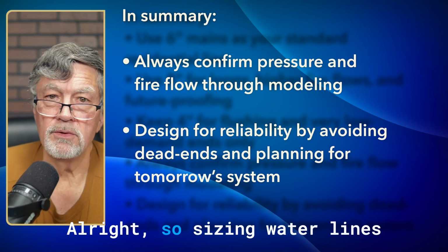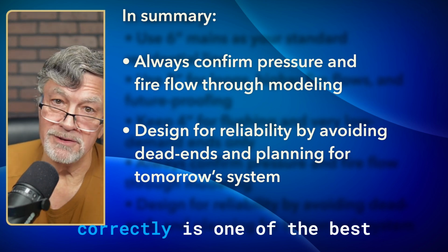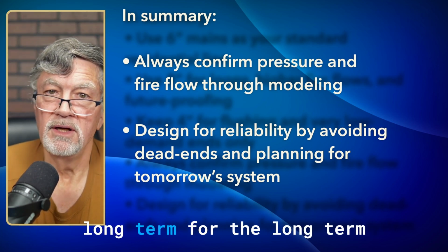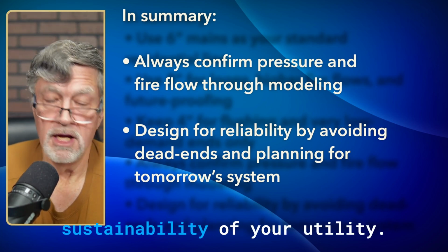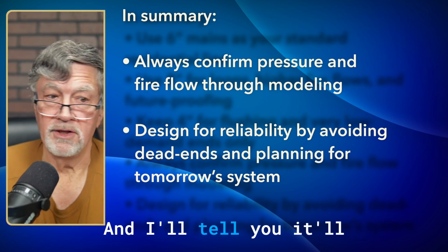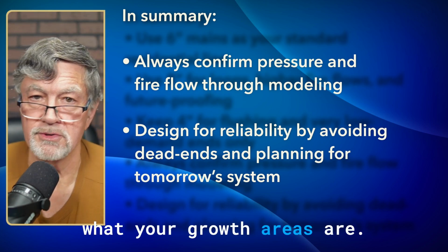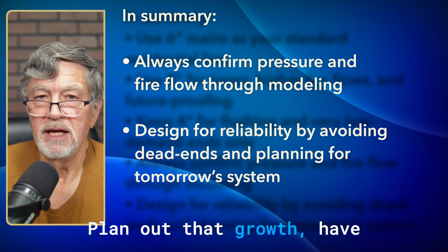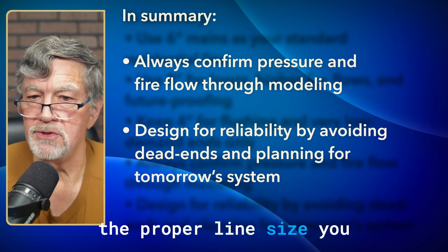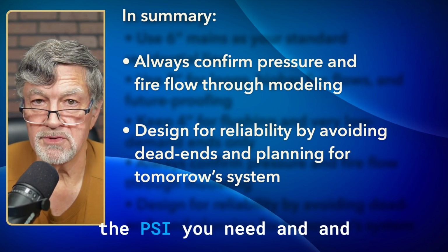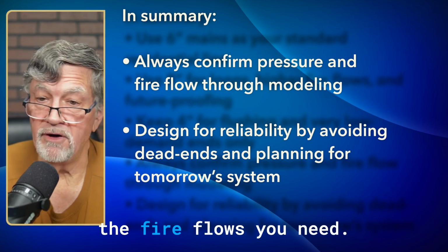All right, so sizing water lines correctly is one of the best investments you can make for the long-term sustainability of your utility. And I'll tell you, it'll reduce your headaches so much if you really look at what your growth areas are, plan out that growth, and have the proper line size you need to support the uses, the number of residences, the PSI you need, and the fire flows you need.